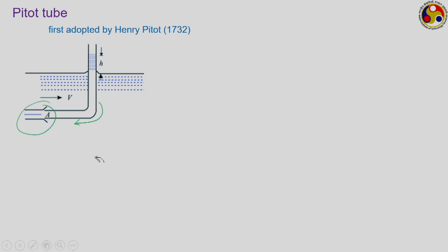is facing the flow. Now, as the fluid comes in contact with this, because this particular tube is stationary, the fluid will immediately try to adhere to the wall, thereby attaining a stationary condition. In the previous lecture we discussed the concept of static and stagnation pressure, so from there I am sure you are able to relate this. Which pressure can it measure?